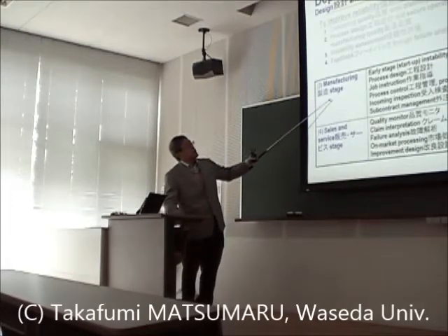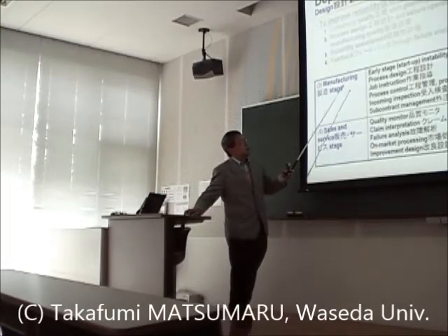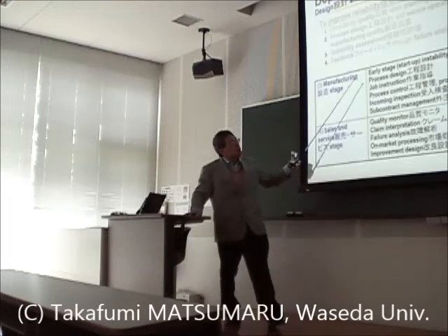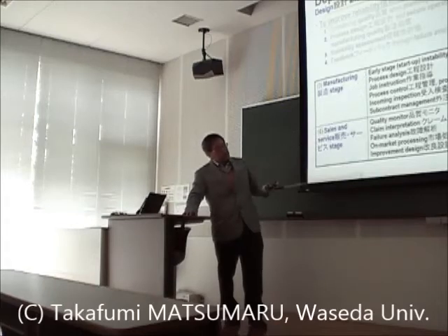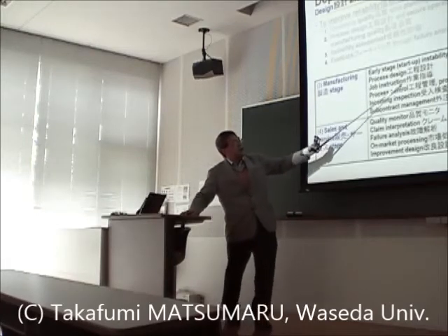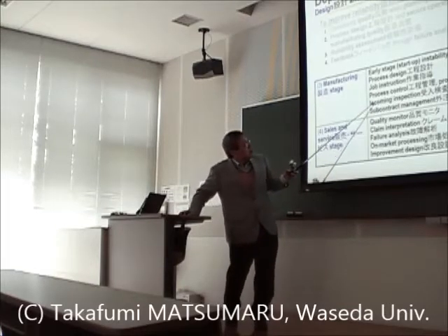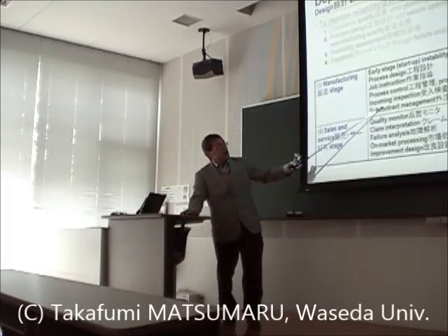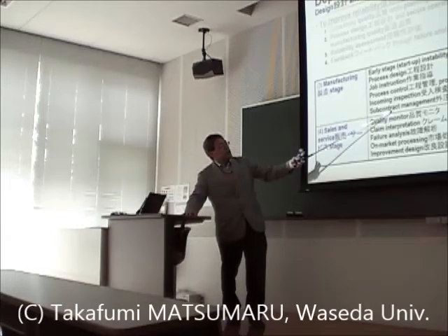And thirdly, the manufacturing stage. While manufacturing and assembling, early stage instability control is needed, because the first starting-up condition is not good and many mistakes are made. So in the early stage you have to take care. Then process design, job instructions to the workers, process control, process check, incoming inspection for each assembling part, shipping inspection after the assembly, and subcontract management.